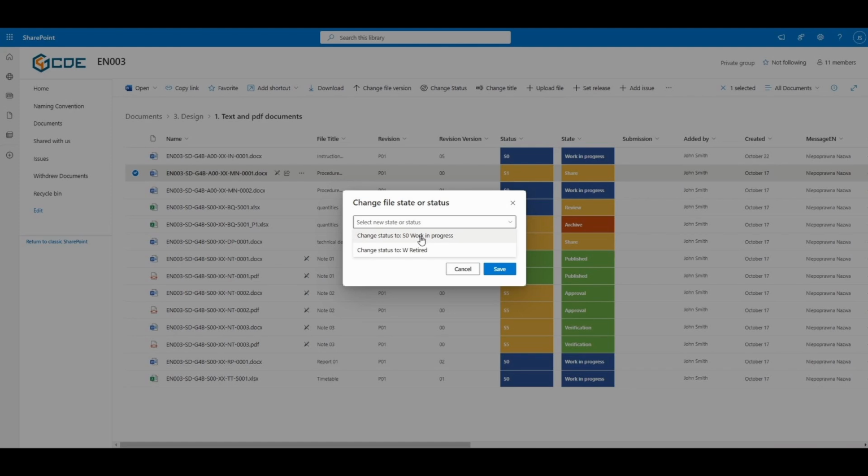The ISO guidelines assist in defining team structures, access groups, and permissions. They provide advice on release processes, including validation, verification, and approvals. This ensures proper handling of revisions and archived versions. Metadata, such as state or status, helps determine file purpose. A well-utilized CDE enables effective collaboration in distributed teams, conflict analysis based on version history, and faster document retrieval.